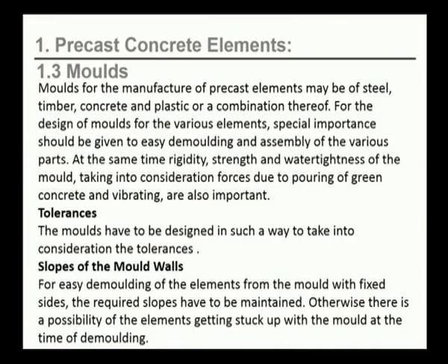Slopes of the mold walls. For easy demolding of the elements from the mold with fixed sides, the required slopes have to be maintained. Otherwise, there is a possibility of the elements getting stuck with the mold at the time of demolding and it will spoil the concrete.